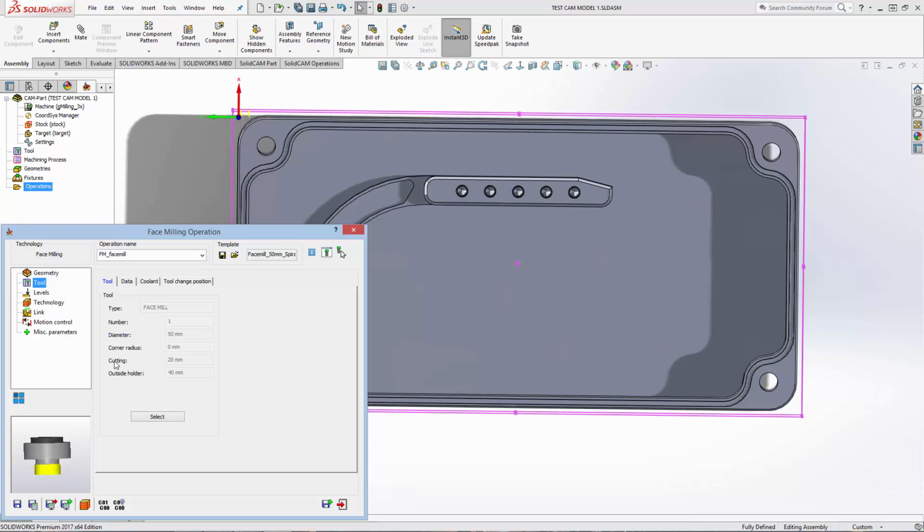It has a cutting height, which is what this 20 is, 20mm, so that upright there, which is also coloured yellow, will also cut material. So you could send this tool into the part sideways, as long as it's not cutting deeper than 20mm, or depending on the type of tool that it is, sometimes you can enter from directly above. But the yellow portion there represents the bit that is toothed, that can cut away material.